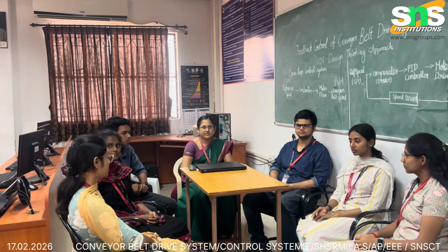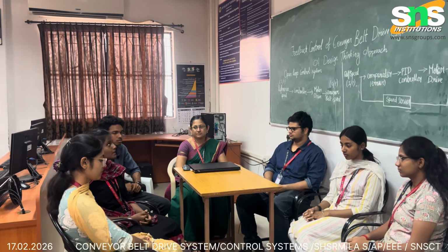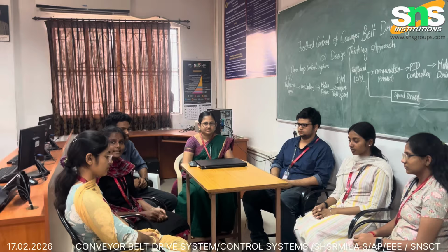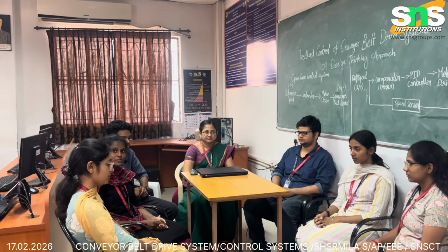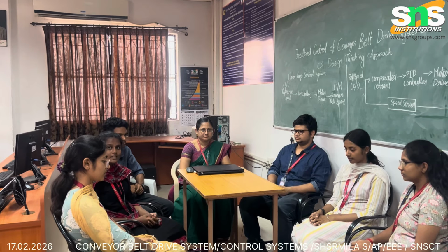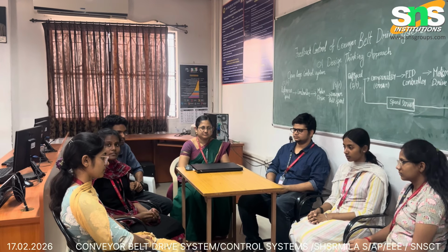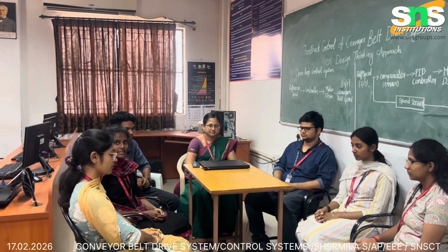Let's move on to the testing part of this problem. Now we talk about the testing of a conveyor belt drive system. We have several factors to analyze: rise time, settling time, overshoot, steady state error, and stability. If the conveyor is too slow, we have to increase the proportional gain, and if the speed is oscillating, we have to adjust the derivative gain.